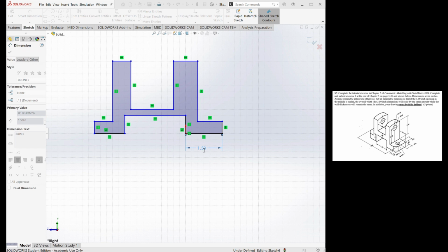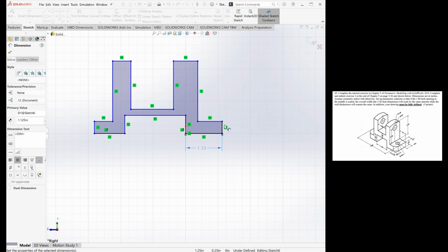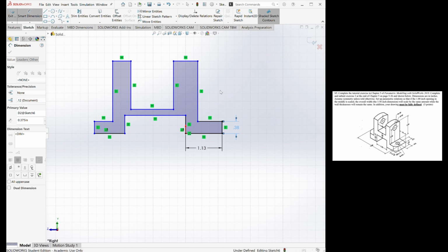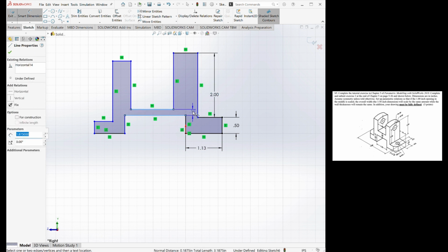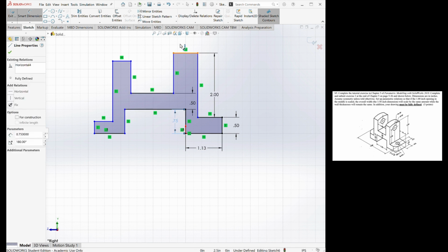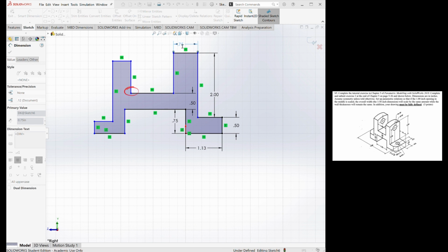But now when we get to the dimensions, there's going to be a couple of rules that we're going to want to follow. Don't make any overall dimensions. And make sure that every dimension on the arm that is on the side opposite the origin goes back to 1 point on the top face, on that corner between the top arm and the second part of the gusset.